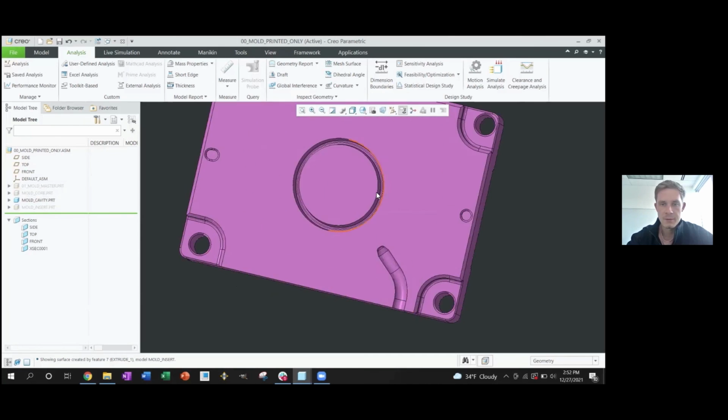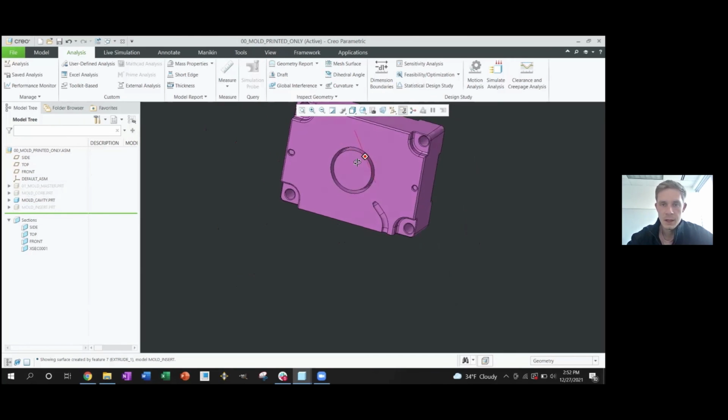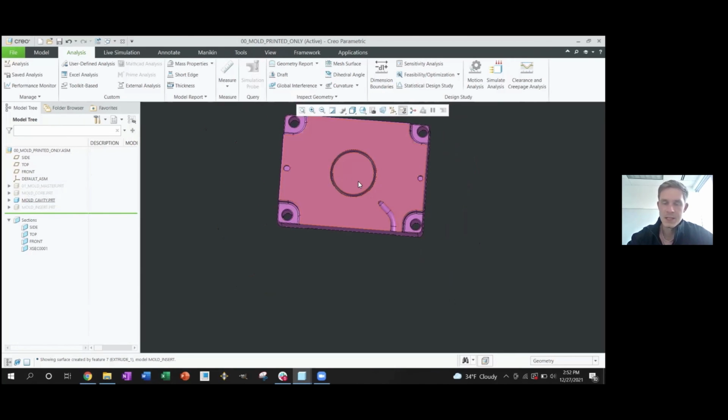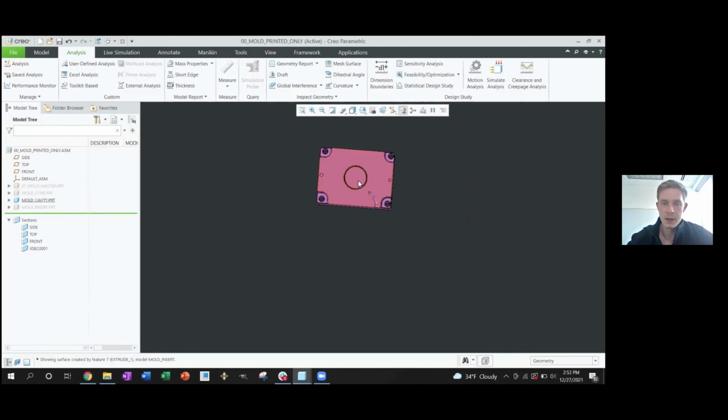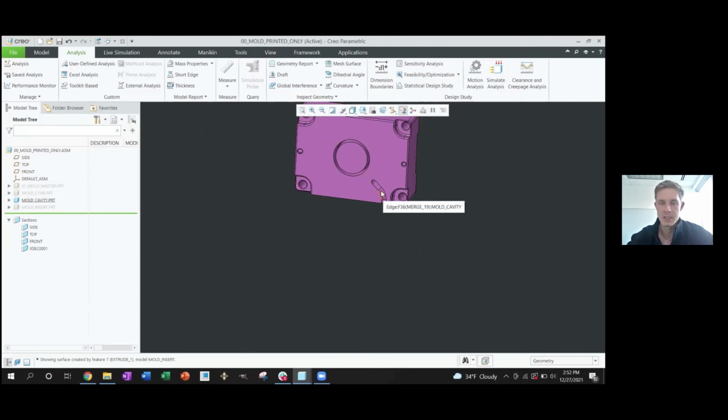For our cavity half, there's no undercuts on this feature, so it does not need to be an insert. Although this geometry, you'll find a lot of inserts that look similar to this geometry, but we've identified the insert, we've created that insert, and we now have a functioning mold that is something we could put into our machine and successfully mold parts.